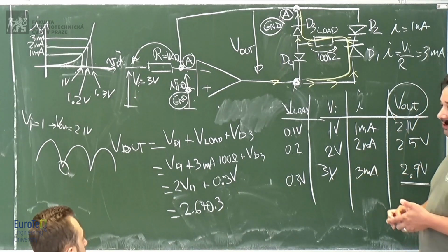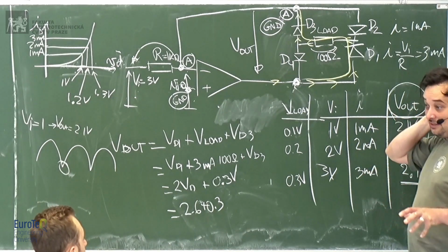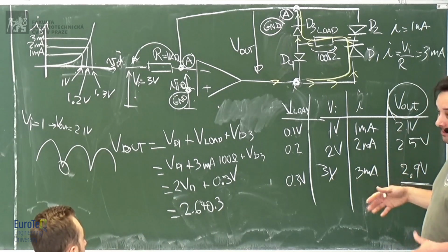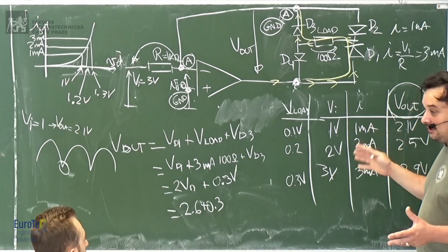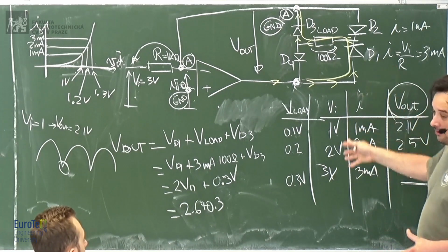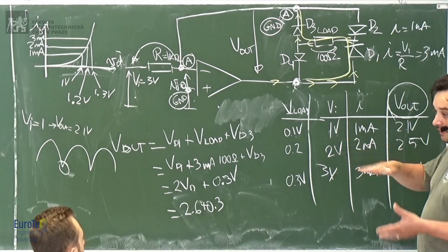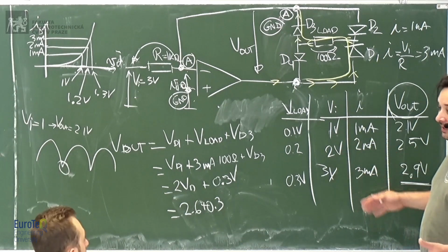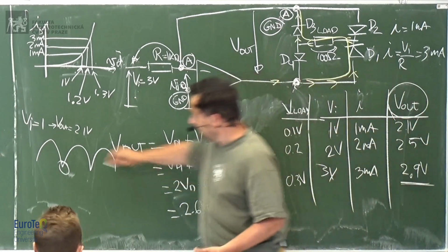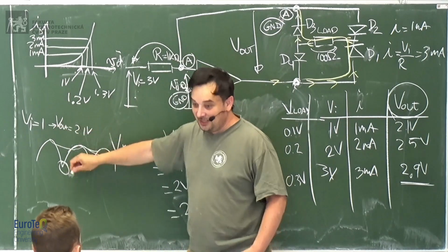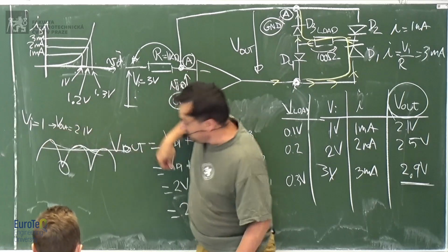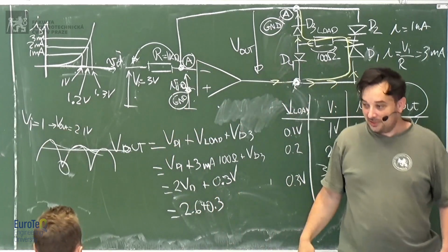Because if your purpose is just to convert some AC to DC to power up some circuit, then you don't care about the precision bridge, because what you do then is put your capacitor, flatten it out, and you get your DC. When you flatten out, who cares if it's non-linear? It's just 0.6 V; at the end you just go with the DC voltage.